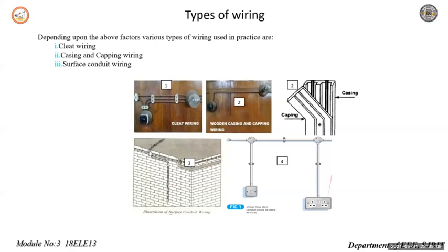Like that, even metal sheathed wiring is also there. That is actually not that important, but in this type of wiring, vulcanized India rubber conductors covered with a lead alloy sheath are used. It is similar to CTS or TRS wiring. So this is about different wiring schemes. All the types we have covered now will be used for domestic purposes, domestic wirings. So that completes types of wiring.